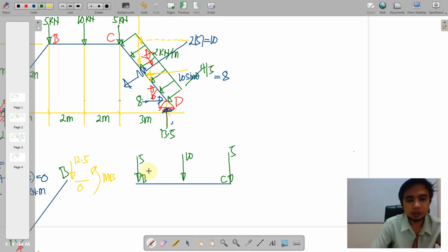Okay, we place initially these external forces and reflect the opposite or the reaction of this 12.5 coming from your first member, that's 12.5. So this is downwards, so it should be upwards when it is transferred on your beam. Similarly, we have for the couple, if this is a counterclockwise couple, so we place it in a clockwise manner on your beam. Okay, so we may place the value 37.5.